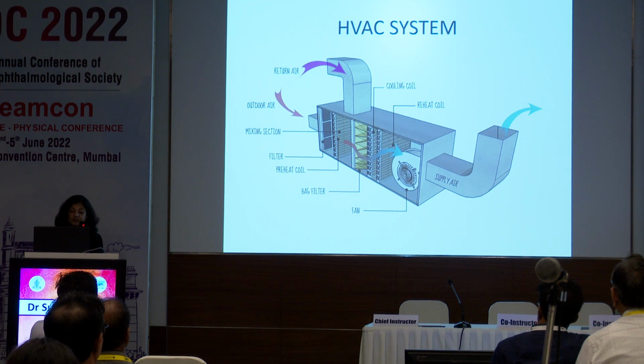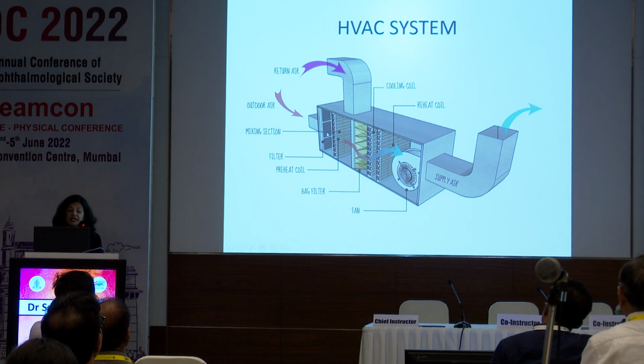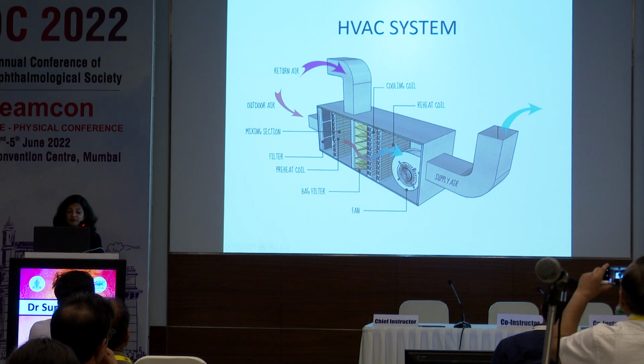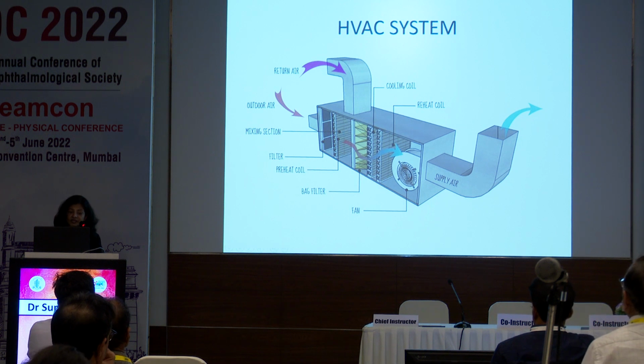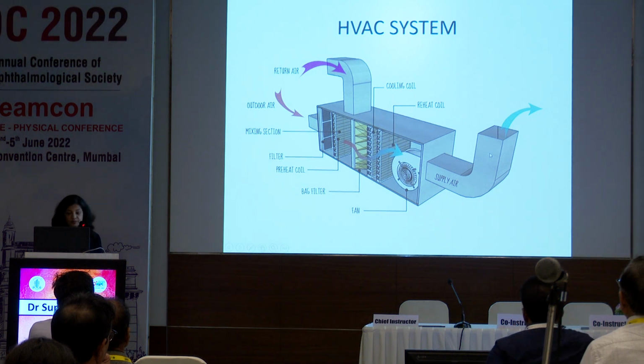The first chamber has provision for entry of return air and fresh air inlet. Air in this chamber is mixed and then passes through a set of 5 microns filter into the second chamber. In the second chamber, the air is cooled, compressed, and then blown at a desired pressure, and then passes through a set of 3 microns filter into the third chamber. From the third chamber, air passes into the airflow plenum via 0.3 microns filter.